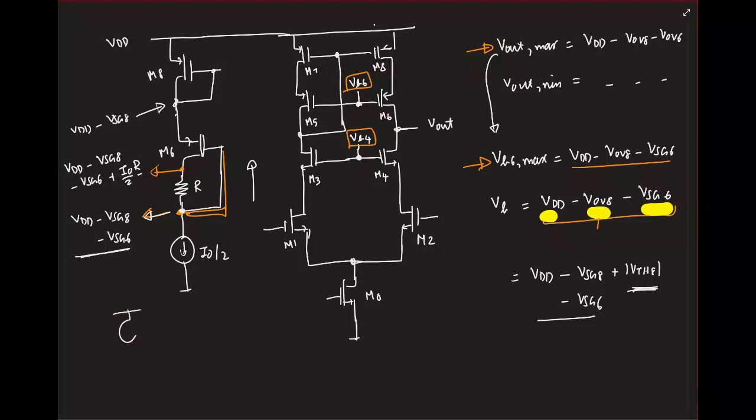So if I do this, I'll do it with an NMOS first so that it's easy. What is this voltage? It's a gate to source voltage. So what is the expression for this gate to source voltage, in terms of the current, mobility, etc.? What is it? Root 2 I by something, plus VTH.